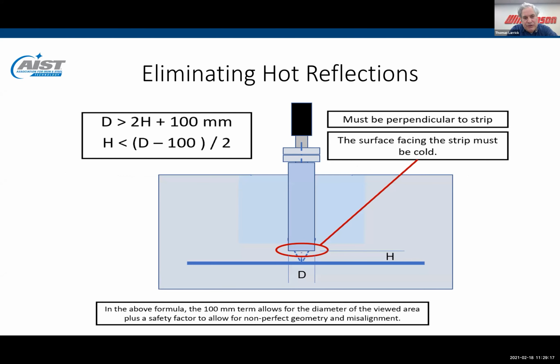The other way to measure inside the continuous annealing furnace is with a cooled viewing tube, or what we call the direct view. With the direct view, the pyrometer views down onto the strip, and it views the strip, as we said, it's 35% emissive, but it's also 65% reflective. And if the background is hot, then we need to make sure that the pyrometer is viewing a reflected image of a cold background in order to assure that the hot background does not influence the pyrometer reading. So the way we do that is to have a cooled viewing tube in those positions where the furnace background is hot. If you have a cooling zone, then you don't need a cooled sight tube. The background's already cold.